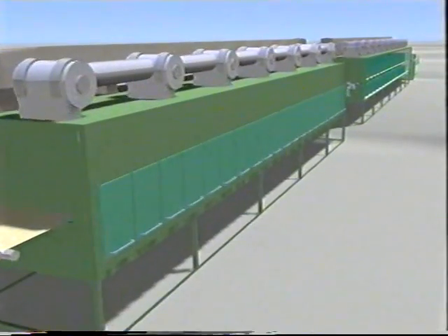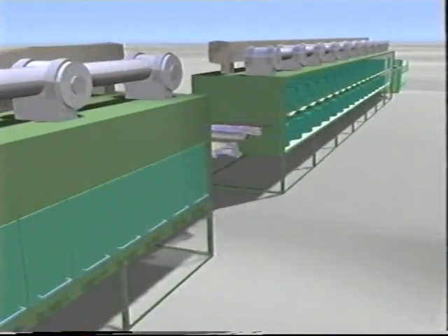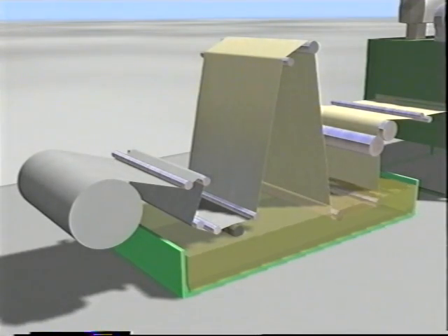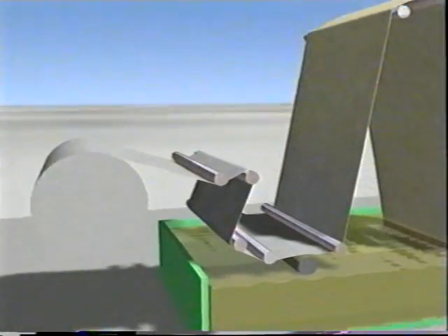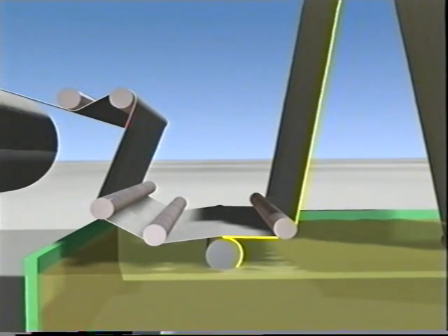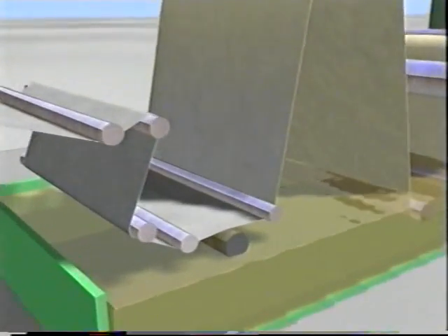With the aid of this virtual impregnation treater, we will demonstrate a two-stage impregnation with urea in the first bath. At the first impregnation station, the core of the paper is filled with the resin solution. A pre-wetting roller applies the resin to one side of the web. The penetration itself occurs after the web has left the roller. The key phases of the impregnation process are wetting, absorption and swelling, penetration, and finally saturation.